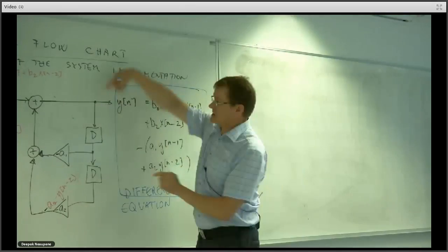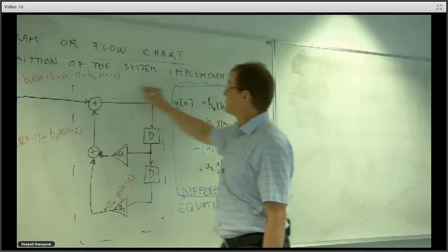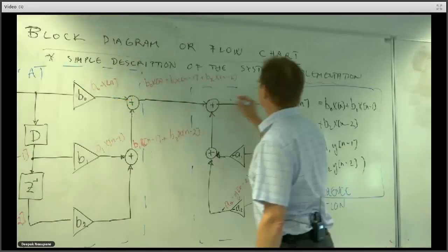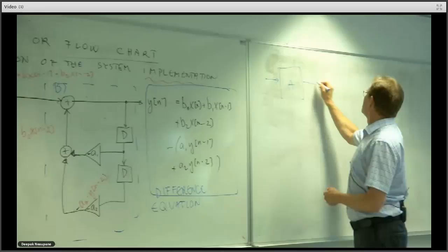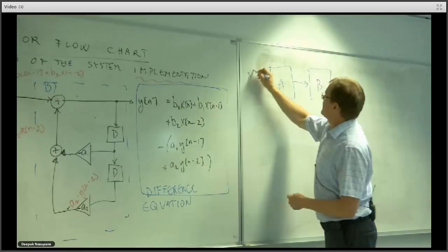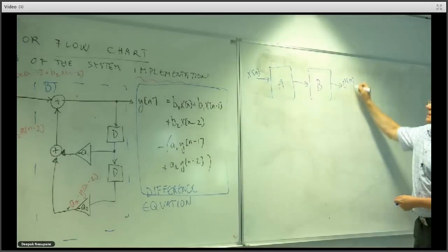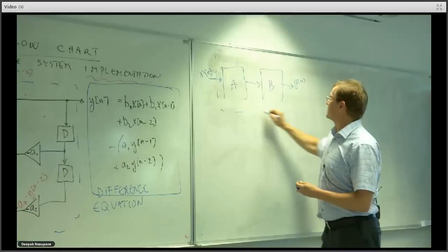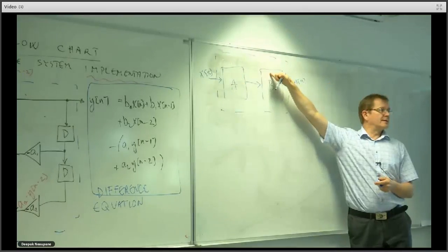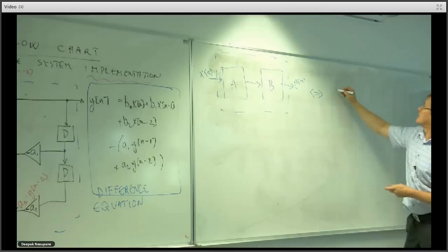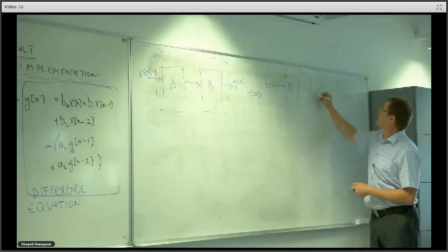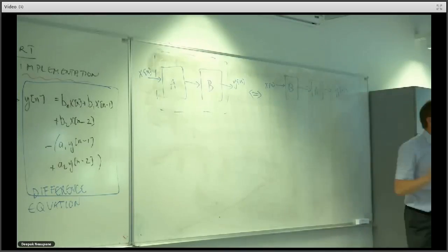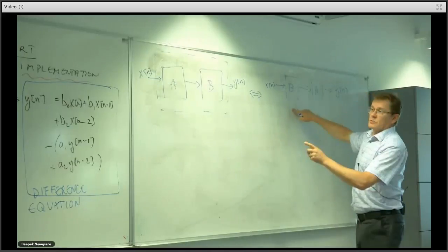basically what you can do is, since these are two blocks, block A and block B, or well, this is the A block and this is the B block. So we have signal x of n going first to block A and then go to block B, and then that's the output. On the other hand, for signal, it doesn't really care. If these systems are linear, then this is exactly the same result if we take first the block B and then block A. If they're linear, and they are. Okay, which means